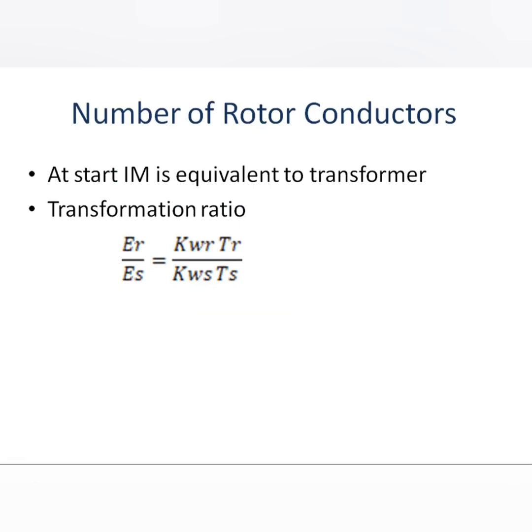The rotor of a three-phase slip ring induction motor basically consists of a core, a three-phase winding and three slip rings. Generally, these windings are connected in star. The three common terminals are connected together, whereas the other three terminals are brought out onto the slip rings, and these slip rings are rigidly fixed to the shaft, on which the carbon brushes rest. Those slip rings can be connected to the external resistance or other sources for the controlling and starting purpose of the three-phase induction motor.